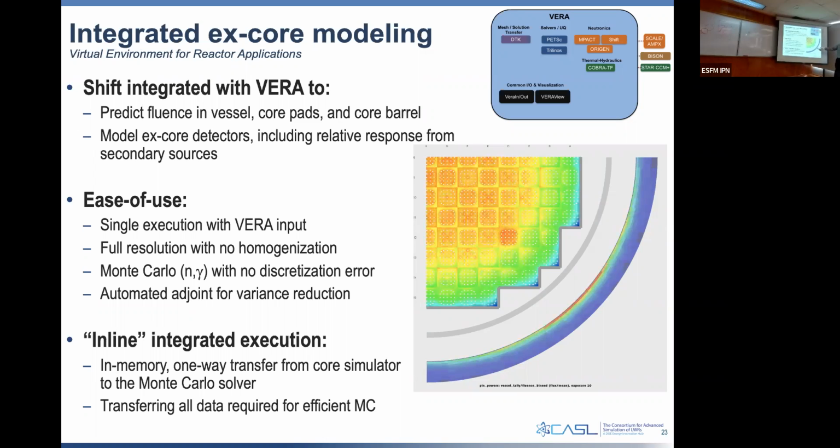And so we have probably 20 different reactors that we have modeled their entire lifetime. And so we've been able to say, let's model the first cycle and the second, third, fourth, 21st, 23rd, to figure out how over the life of that pressure vessel, these fuel assemblies get changed out all the time. This pressure vessel is always there and getting irradiated. How much irradiation has gone there, so we can start to understand what impact is there on the materials.